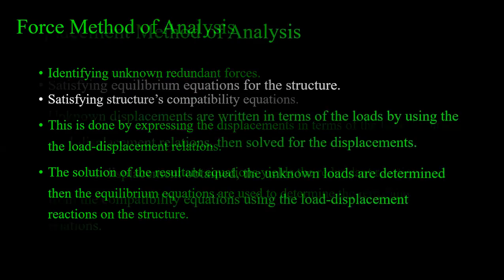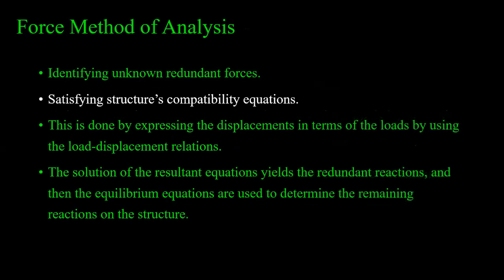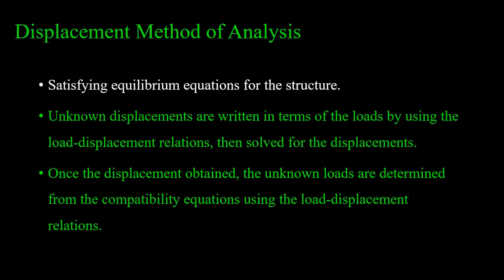In the displacement method of analysis, we satisfy the equilibrium conditions, as we discussed before. There we solve for unknown displacements, considering the equilibrium. Here in the force method, we satisfy the shape of the structure, that means the compatibility, and solve for redundant force. In the displacement method we solve for redundant displacement, and once the unknown displacements are known, we can solve for the unknown forces.